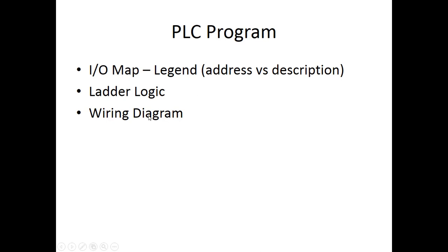And then you're going to turn in a wiring diagram. Once again, the wiring diagram shows the source and the sink, and it shows the actual symbols. So this shows the NEMA ANSI symbols. If it's got a push button, 1 PB. If it's got a contactor or a relay or a solenoid, 1 SOL. The wiring diagram is going to show where those connections are made. Once again, used for troubleshooting.